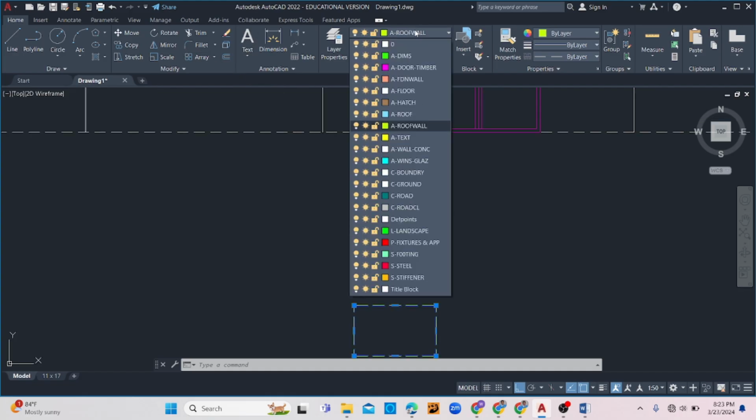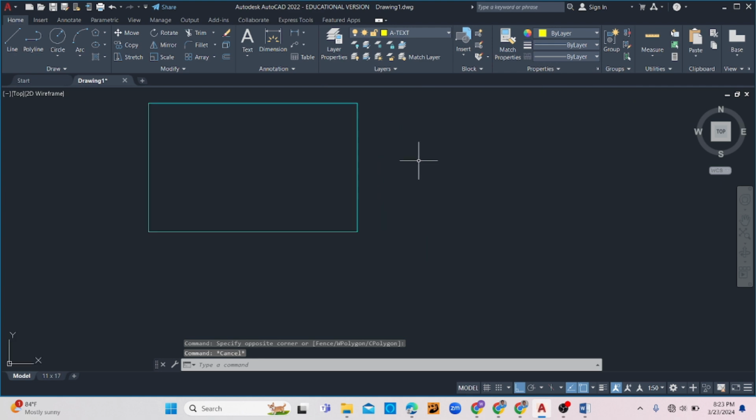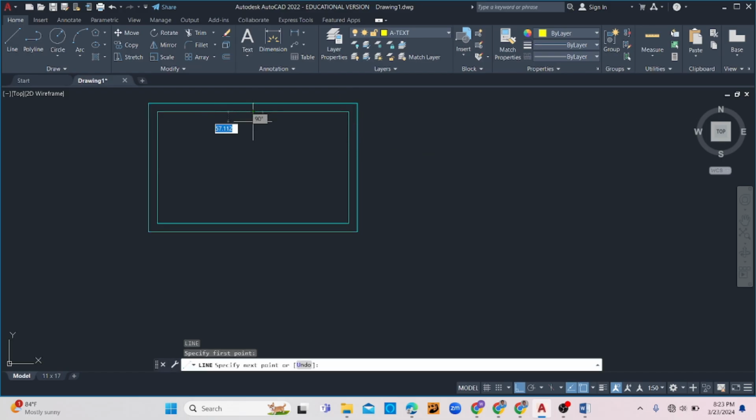So let me paste this on my windows layer, I should have one. Let me look. Alright, now once I have that in place, let me offset the 50, and then let me draw the line in the middle, and offset 50 on either side.